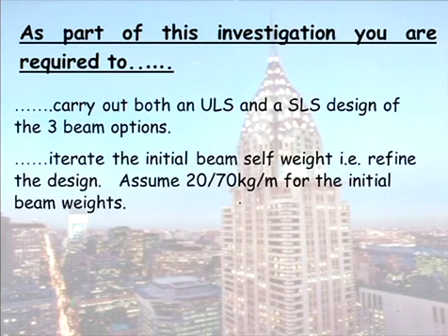In Truss 1, Project 1, you actually said, let's just guess the members weigh 10 kilogram per metre, 15 kilogram per metre. Then you got to the very end, you worked out what they did weigh and said, well, I was conservative, we were unconservative. This time round, you have to iterate. You have to start off with a weight, do the calculation, actually calculate how big your member has to be, put that weight back into the calculation. The iteration comes out in 2 or 3 iterations. It takes no more than 3 iterations.